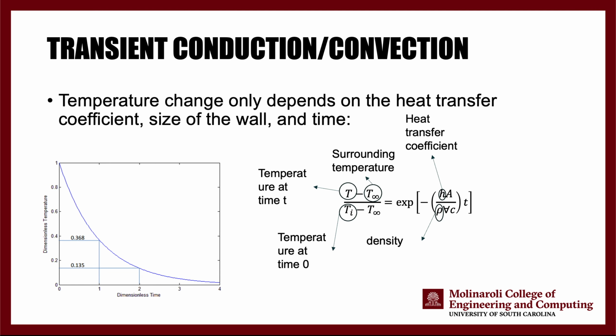So this heat transfer coefficient multiplied by the area of the copper block, this is a cube, so 6 times the area of each side of the block needs to be included, multiplied by time that has passed, divided by the heat capacity of copper, multiplied by volume of the copper.